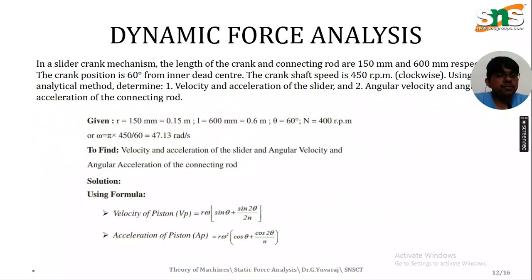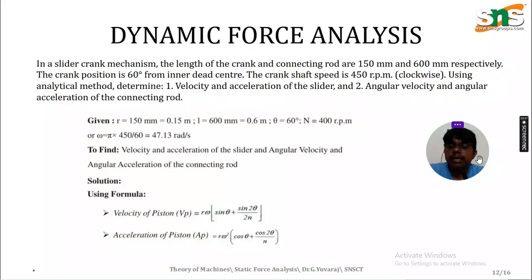So let me discuss one problem. For example, we are going to deal with the dynamic force analysis of a specific engine component. The given problem is about a slider crank mechanism. The length of the crank is 150 and the connecting rod is 600, the crank angle is 60, and the crank speed is 450 rpm, rotating in the clockwise direction. Using the analytical method we have to calculate the velocity and the acceleration. We know that we have to use the formulas.